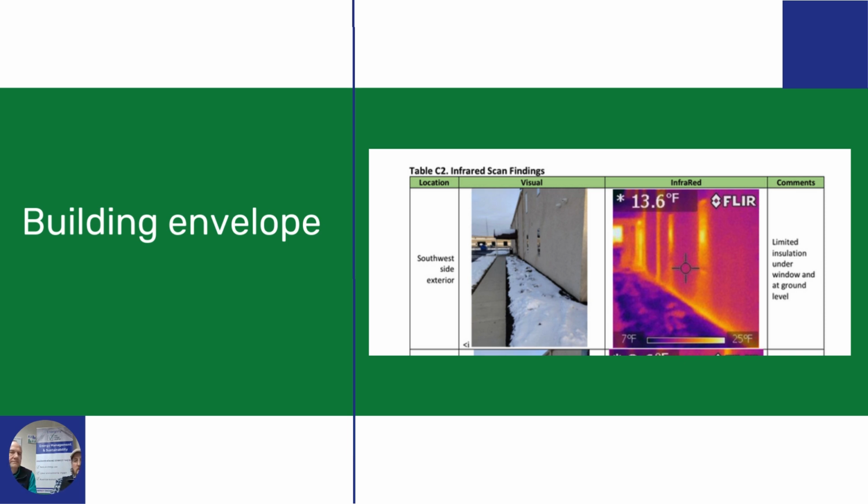But when we start, we don't exactly all have X-ray vision, and the infrared camera gives us the best ability to take a very basic, simple concrete wall and see, hey, maybe there's some insulation impairment, or maybe there's a connection where there's what they call thermal bridging. Some things you can't do anything about, but you can make a knowledgeable choice or have an awareness about a situation.